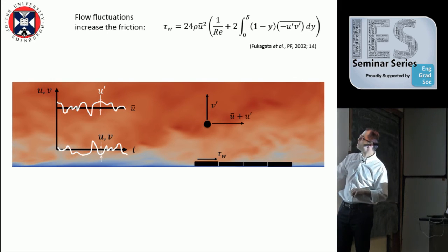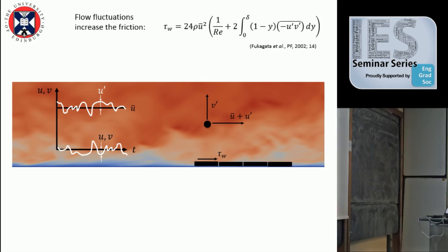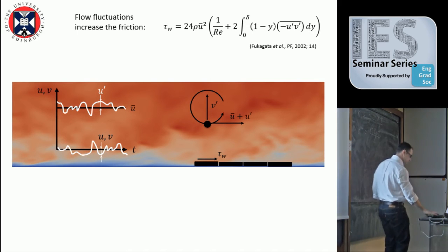And just to clarify, if you put an anemometer here, so if you measure the velocity at this point, what you will observe is that the flow will keep varying in time, and you will have a mean value. What we are interested in are the fluctuations, and we're not concerned about the mean value. Of course, in the streamwise direction, there will be a mean value. In the y direction, in this direction here, there will be no mean value. This is probably a mistake.